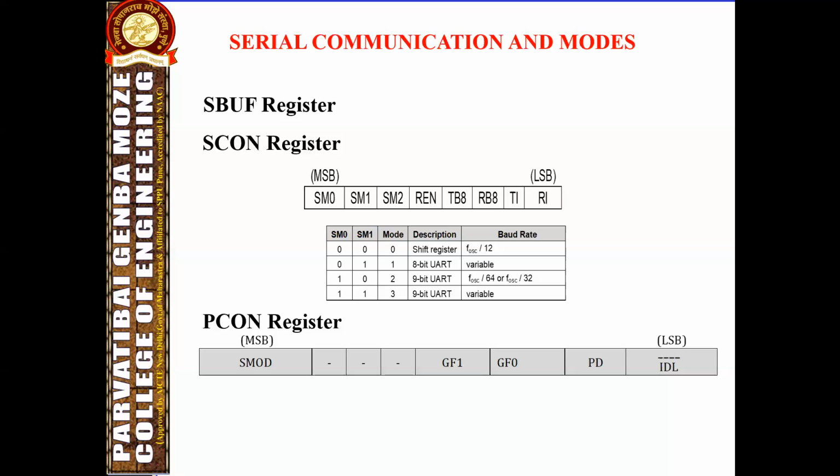The 8051 serial communication UART circuitry divides the machine cycle frequency, then feeds it to Timer 1 to set the baud rate. The 8051 baud rate is set by the timer using mode 2. To get baud rate compatibility with the PC, we must load TH1 with the value shown in the figure below.